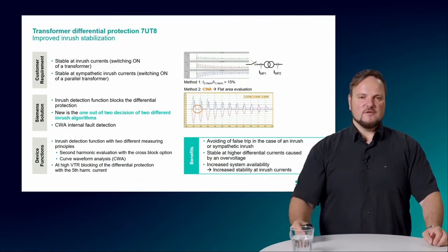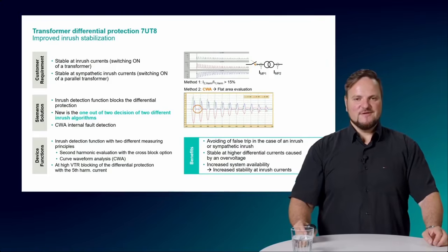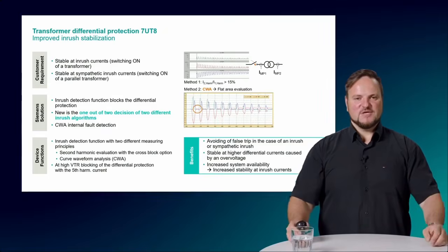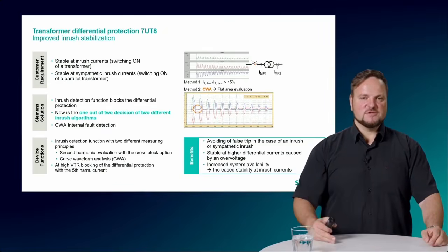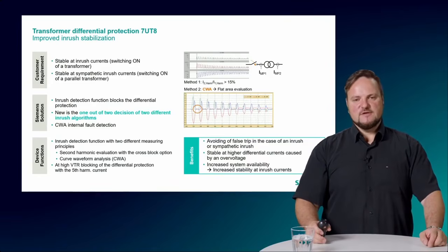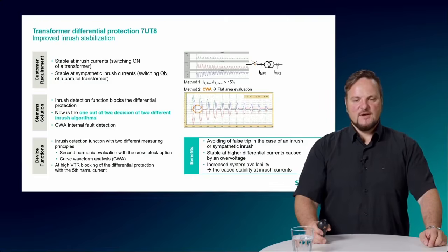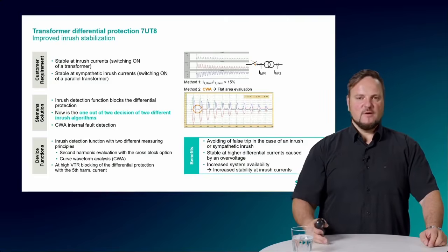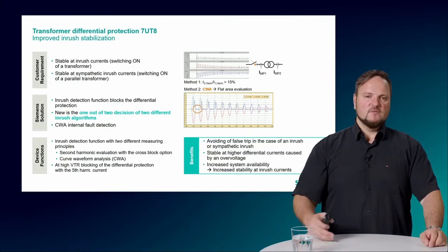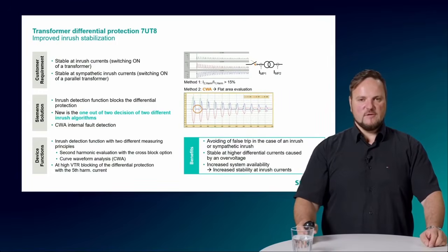And of course, also the transformer manufacturers are making some changes due to noise reduction in the transformer, to decrease the losses in the transformer, and therefore also new transformers with new core materials do not inject so much second harmonics. So therefore it is really good to have here a second method to energize the transformer.